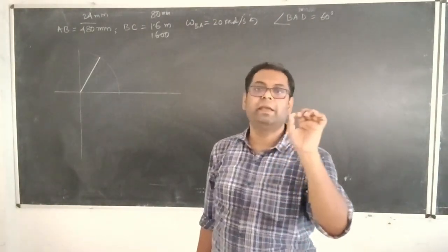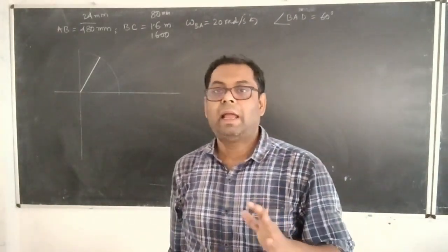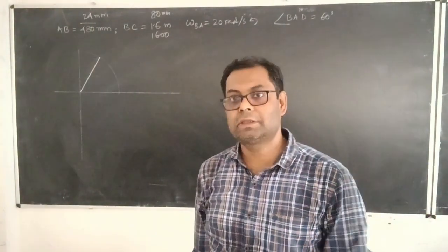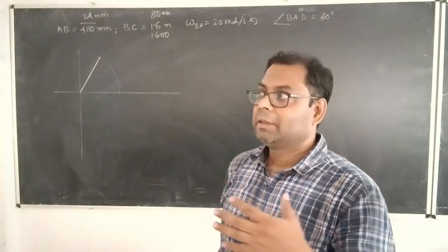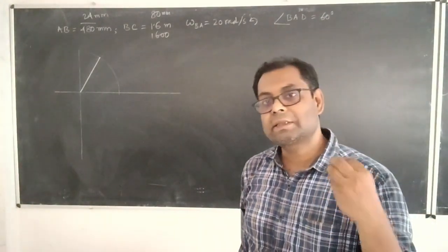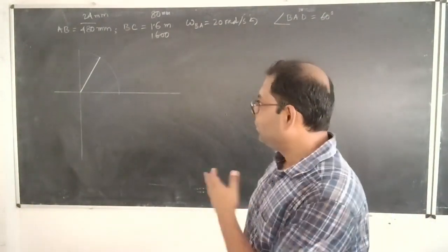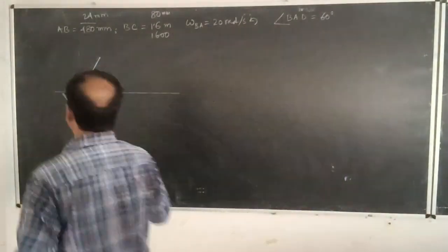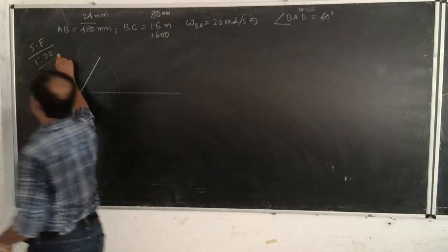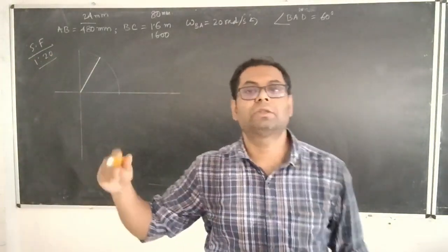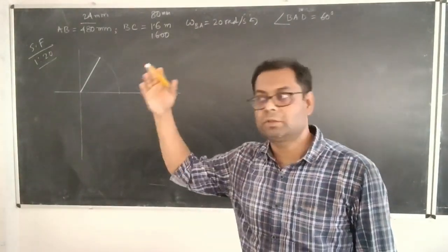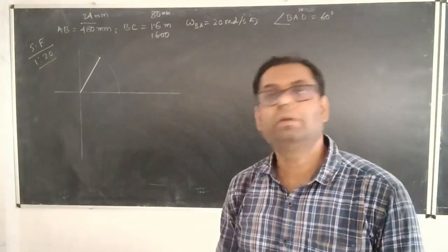So scaling factor is a very important thing. And let me tell you one more thing, there is no such hard and fast rule for selecting the scaling factor. Suitably and judiciously, we have to choose what scaling factor I am going to take. So over here I have taken a scaling factor value of 1:20 for the space diagram. But if you want to take 1:10, 1:15, 1:25, that will also work.